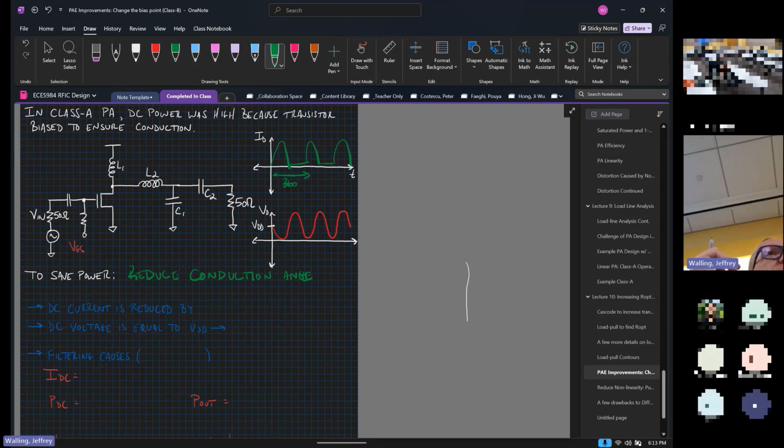Well, in a push pull, the only thing is that you're effectively getting a full signal swing. It's just that only one transistor is conducting current at a time. So the DC power consumption of each transistor is still lower. Right. But here for us, for RF, it's just Class B means 180 and Class C is less than that. Yeah. Like a circuit topology. Well, and we will make push-pull Class B amplifiers as well.